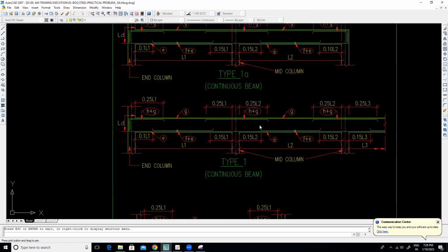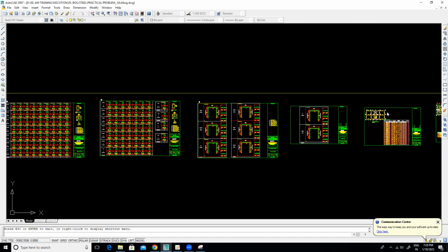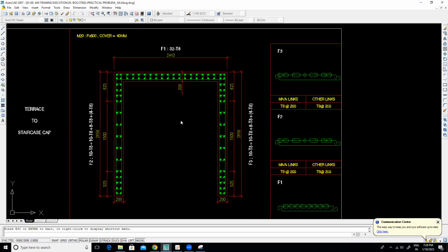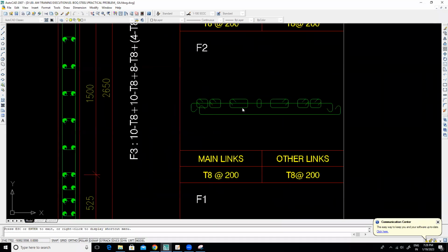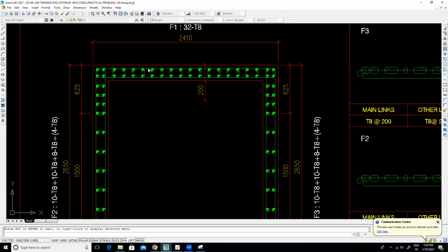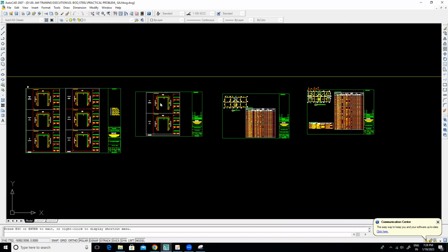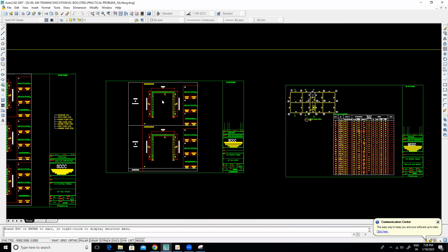Now we will go to the next topic. Is there anything different here? No? Regarding the shear wall details, I will keep it with you because you need to calculate all the lengths like this. Generally we get the details from the RCDC and it will do the calculation for us. And if I ask you to do it manually, it is still easy. You can measure this dimension from the AutoCAD and calculate the length of each hoop and link. And finally, you can calculate the steel, right? I'm not going into detail. Once you understand the concepts, it is the same for all.